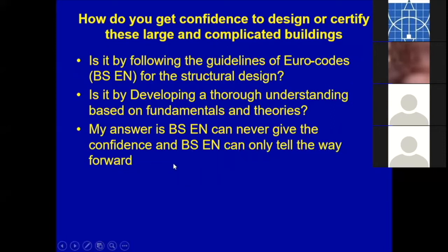And what is BSEN? That is the Eurocode. The BSEN is the English version of the Eurocode, and you can use the national annexures. So if you don't have a national annexure for SLS, the procedure is simple. Simply use the national annexure for UK, because you can get a reasonably good comparison, because they also have fairly warm summers. The summertime temperatures can go up to about 30 degrees. Anything applicable to them can be applicable to us, because ours also, being an island, our average temperatures remain in that range. So because of that reason, you can always make use of the national annexure of UK if you don't have a properly completed national annexure.